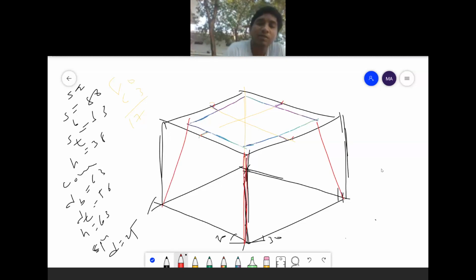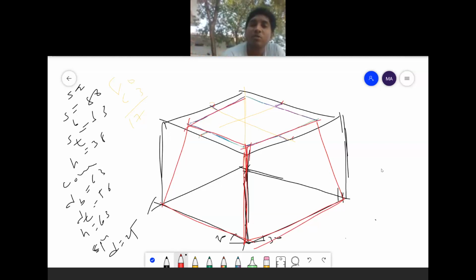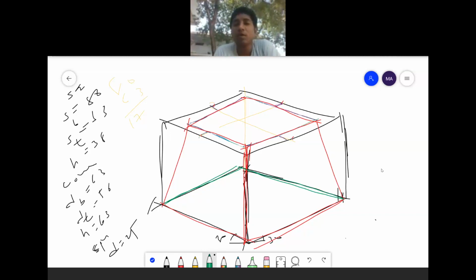This one which I am drawing with a red pen should be dark. Understand? It is your main diagram. Then the other pen, the green pen, should be a dotted line. All the other black pen should be very light. Those are all for construction purposes. This one will be your frustum of a square pyramid.